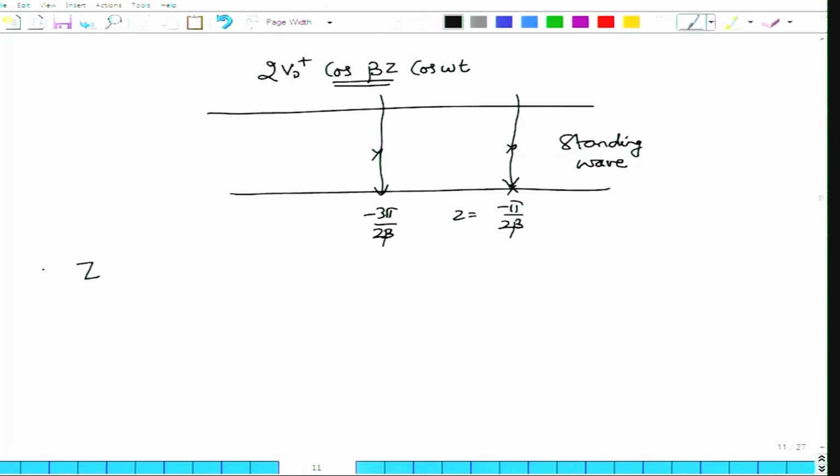Alright, let us consider the second case. I consider ZL equal to 0, which happens to be the short circuit condition. In the short circuit case, I know that the voltage would actually drop down to 0 and the current would actually be maximum there. Okay. But what would be my load reflection coefficient here? Gamma L will be equal to -1, right.